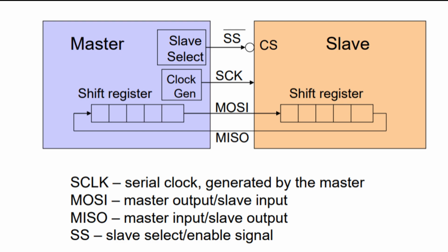That's a very practical point. The slave can't initiate communication, so the master needs a way to figure out when the slave is ready. There are a few common methods. 1. Status register polling. This is probably the most common. The master periodically sends a specific read status command to the slave. The slave responds with a status byte, and the master checks a particular bit, like a data ready flag or an operation complete flag within that byte. When the bit indicates readiness, the master then initiates the actual data read command. Flash memory WIP polling is exactly this pattern. They keep asking, are you ready yet?